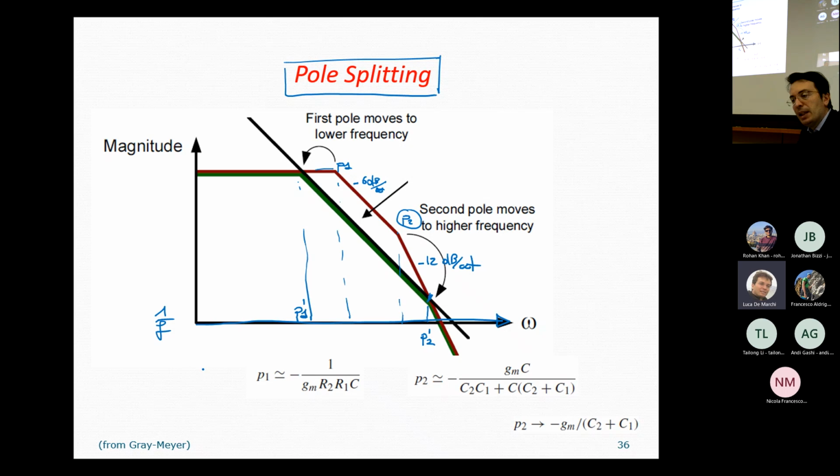Okay. So basically, starting from VDD, we need a VGS here, so minus overdrive of transistor 3 minus threshold of the PMOS transistor. Then we need an overdrive here, so minus the overdrive of transistor number 1.